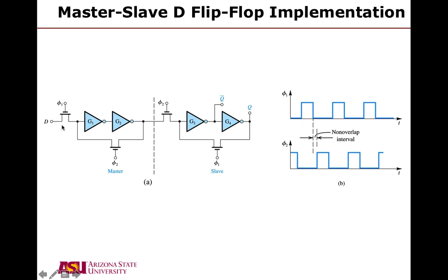So we open switch phase 1 before we close phase 2. And we do this with something called non-overlapping clocks. And non-overlapping clocks are generated still based on the same input clock, but we can generate 2 phases based on that one single input clock. And further on into the slide set, I actually have some interesting circuits, and one of them is a non-overlapping clock generating circuit. And you can look at that at your own time.